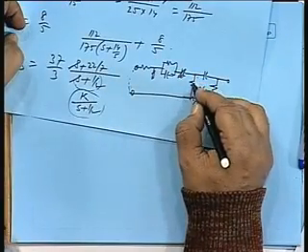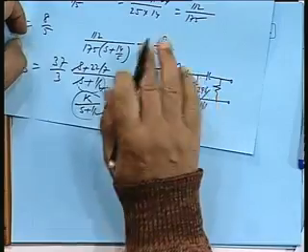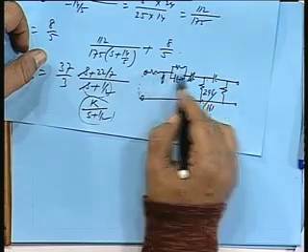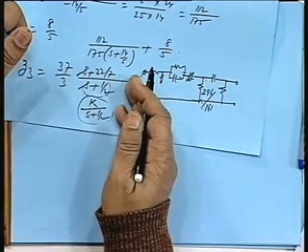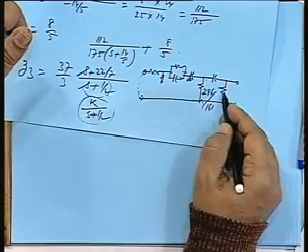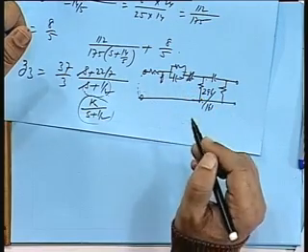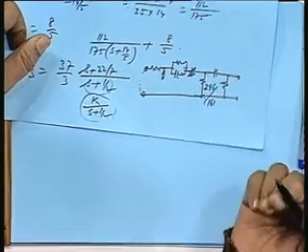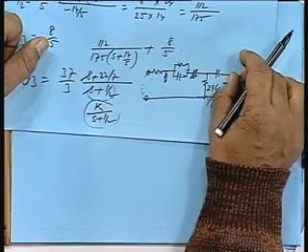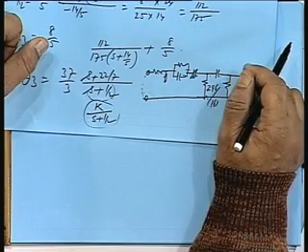So, after realizing this resistance, whatever is left over, you invert it, that will be the Z, and that is just a simple RC and R combination. So, you leave it there. So, this will be your Y22 and Y12 specification made. Obviously, Y11 can be anything, there is no unique choice. I could have removed that 0 at minus half earlier, so I could have got something else. This RC combination could have been at the beginning itself. Do you get my point?